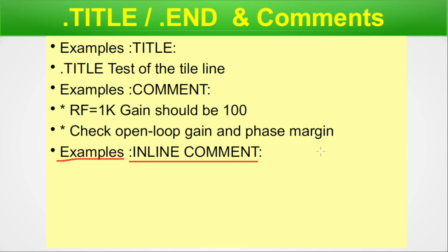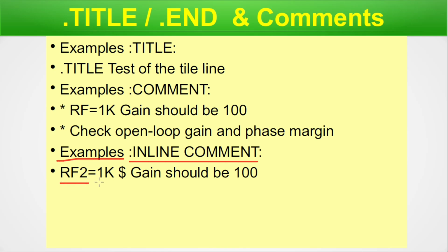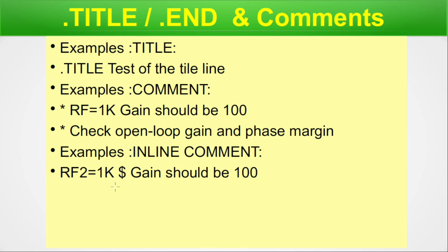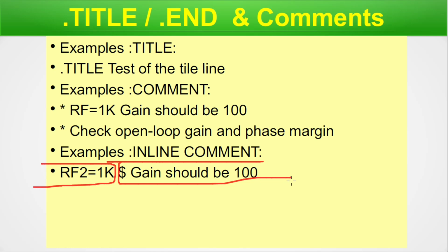Example of an inline comment is like that: RF2 equal to 1K, then dollar, gain should be 100. So this part of this particular SPICE line is a comment. Basically anything that is beginning with dollar in between a line is a comment. So this part is commented out. Up to this will be read by the SPICE simulator. Let me clean it and say it again. So this part is processed by the SPICE simulator, while this part is excluded from the SPICE simulation. So this is treated as an inline comment or end of line comment.